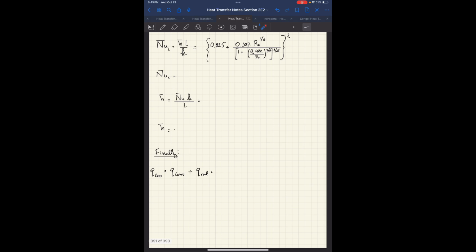And there it is. Okay, you plug in your values, and your Nusselt number should be 257.1. Then you use the general equation of Nusselt number. You invert it, Nu k over L. Okay. And you find h. Smooth sailing so far.